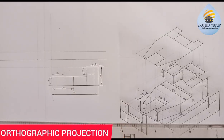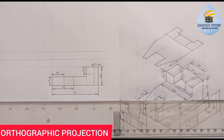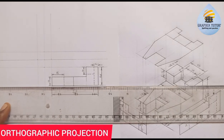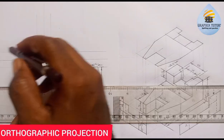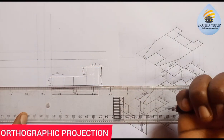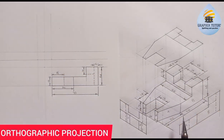Now the next thing is the end view, looking at it from the front here, as the diagram suggests. What I'll do here is I'll project this on this point. I'll take it here, faint line. You can see that. Now the entire length for the front elevation is from here to here. When you're looking at it from the front, you're going to see this part here, which is A, and that is A. This is B, this is also B.